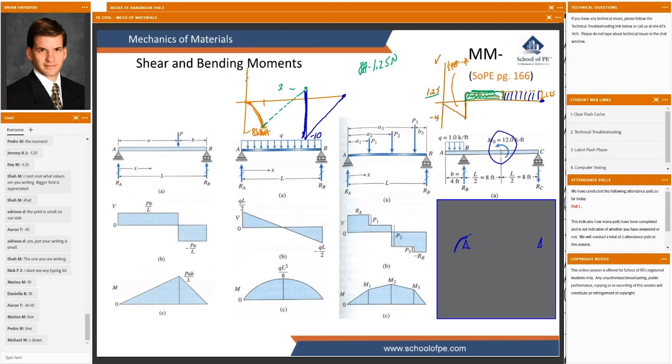It's going to make the left-hand side look a little positive and the right-hand side look a little negative in bending. So you think we've got a little bit of a twist like that in the center of the beam, where just to the left of it, we've got positive bending, and just to the right of it, we've got negative bending. And then that negative bending trend is going to continue to the end, and this brief positive trend is going to continue down that way.